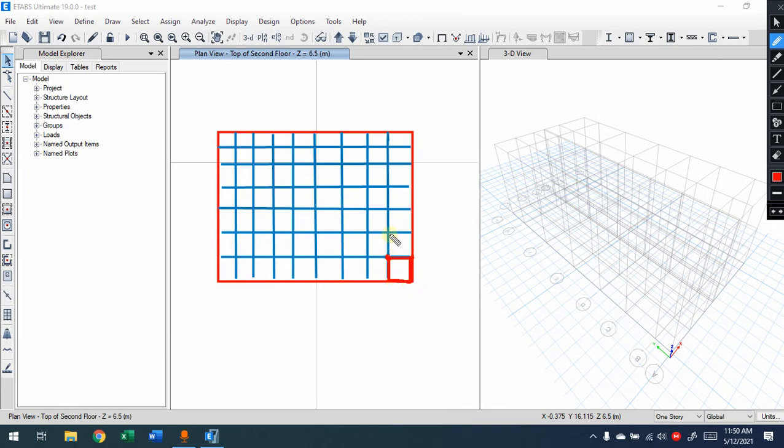Those are the joints we have. All those will be joints. Since ETABS is going to use this method for analysis and design, we have to make sure those joints, in reality, are moving together. If you apply force here, it does not mean that there is a joint there within the slab. No, if this joint here, for example, moves 1 millimeter, this is supposed to move 1 millimeter like this, and so on. This is the aim of the diaphragm that we have to apply to the slab, because slabs will be designed with this analysis and design with this meshing.